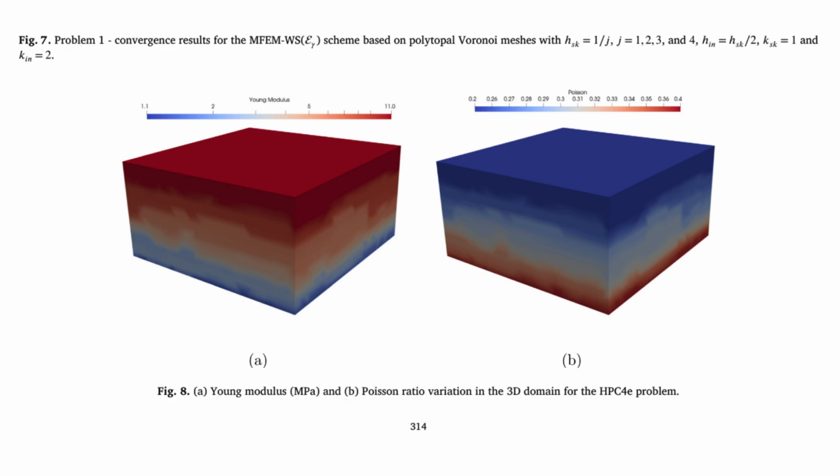Okay, good confirmation. But wasn't there something even more striking about efficiency that came out of a different test? The space-based convergence study. Ah, yes. That was really interesting. Instead of the standard approach where you just make the entire mesh finer and finer to get more accuracy. Which makes the global problem bigger and bigger. Exactly. Instead, they kept the overall coarse structure, the macro partition, fixed. They only refined the mesh on the skeleton and the mesh inside the elements in place. The question was, how much accuracy can we squeeze out of this fixed coarse layout just by tweaking the scales?